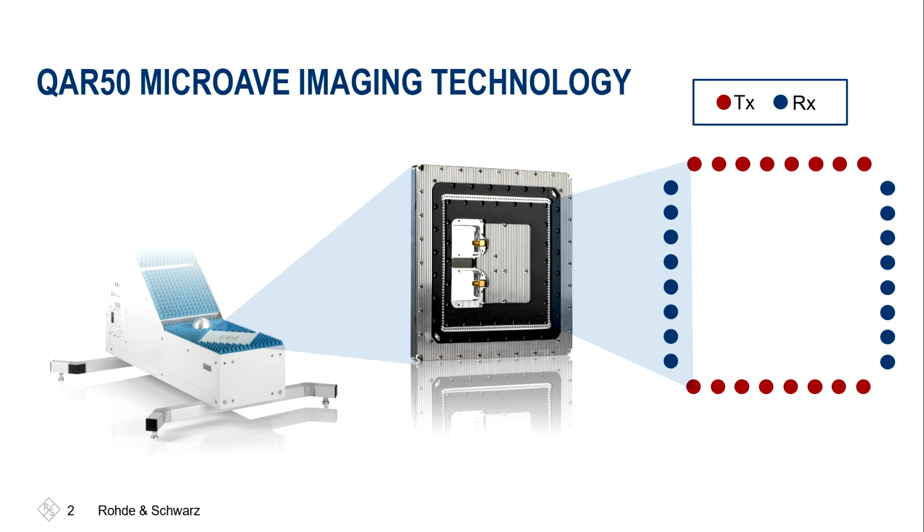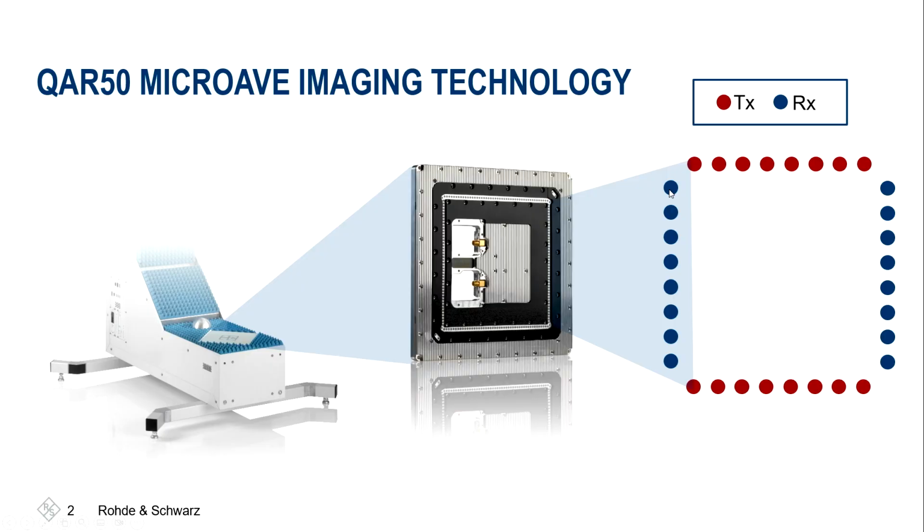So the clusters consist of 96 transmit and 96 receive antennas, and they are positioned in a way as it is shown here on the right-hand side of the slide. The cluster itself is 45-degree tilted inside the QAR because the antennas are 45-degree tilted. So by rotating the cluster 45 degrees again, we have a horizontal or vertical positioning of the transmit and receive antennas and can therefore adapt to the polarization of the actual radar. On the right-hand side, you see the line of RX antennas and the line of TX antennas that we are using in order to create the image.